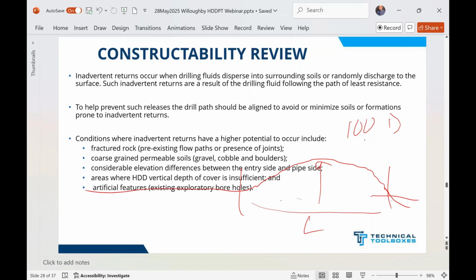And we do it the same way you calculate the allowable spanning distance for any above ground pipe. If you were in a reg station or a meter station or whatever, we have those calculations based on the weight of the pipe and the length of the span. And we calculate that and we give that to the contractor in our specs. And just say we tell them, okay, any elevated pipe has to be supported at least every 40 feet because of spanning stress.